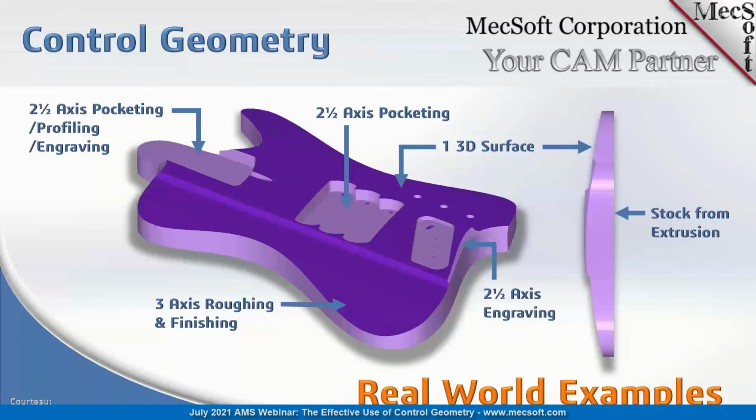And since you don't have any closed surfaces, not a solid model or anything, you won't see the actual part until you simulate the toolpaths. So what we're looking at is the final cut material simulation. We have a stock from extrusion. So we got one profile curve around the entire part defined as a stock by extrusion.